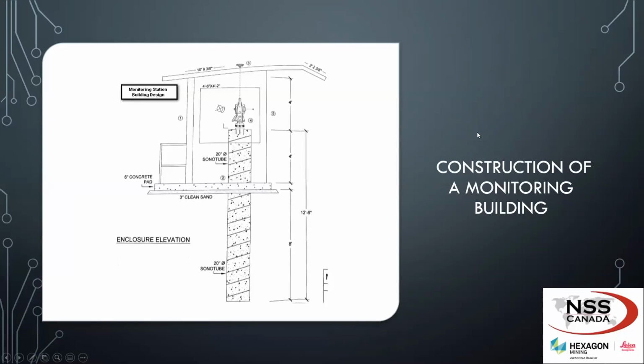This is a basic construction, not so basic. They want the structure not to move. The following monitoring station building design has been constructed for stability, durability, and to acquire the most accurate data possible for Leica GeoMoS monitoring purposes. This is just a recommendation and it does not have to be designed exactly as drawn. This was designed by Leica. This structure has been installed at one of our sites almost exactly like this, and it's been monitoring for about 6 years now and it hasn't moved.